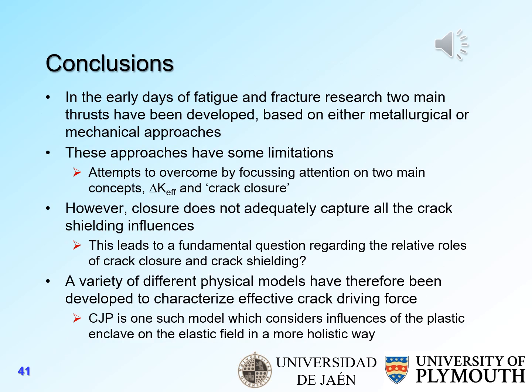So, moving on to some concluding remarks. In the early days of fatigue and fracture research, there were two main thrusts developed, based either on metallurgical or mechanical engineering approaches. These approaches have some limitations. There were attempts to overcome these by focusing attention on two main concepts: delta K effective and crack closure.